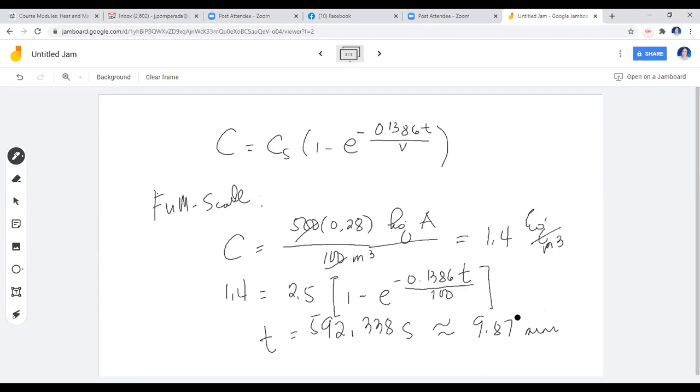Okay? Now, it has to be noted, and I missed to mention this, that in the process of the concentration here over a certain time, how will the concentration of the solution behave against the saturation concentration? So over time, your saturation concentration will exponentially decay. So this is exponential decay. So you see this exponential function. So there will be a corresponding decrease in the concentration of the solution over time as less and less amount of solute, rather, gets to be leached out from the solid.